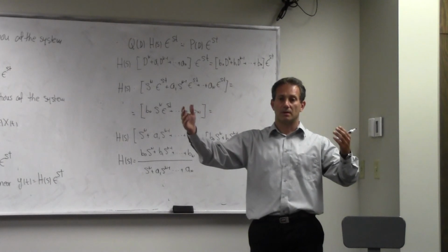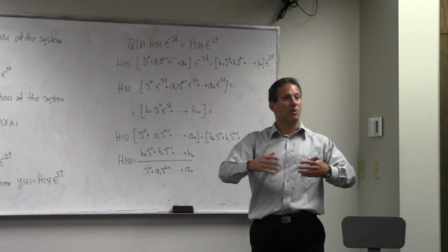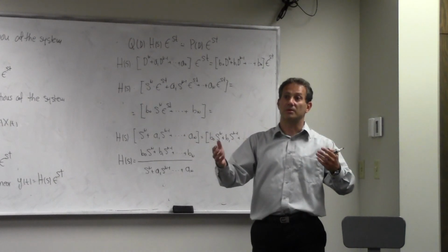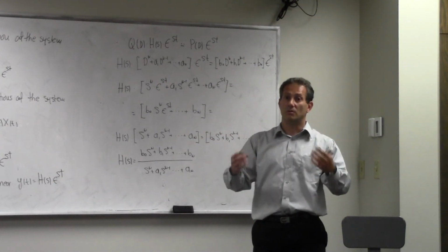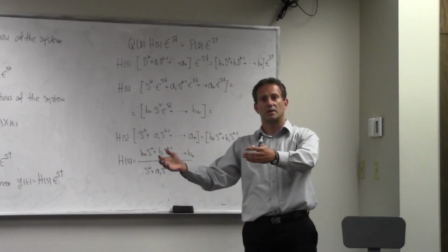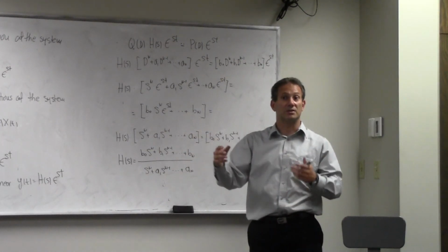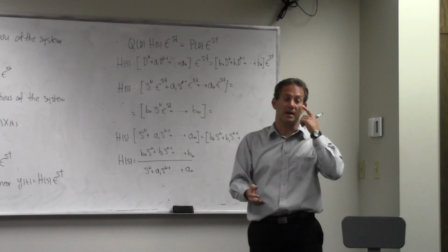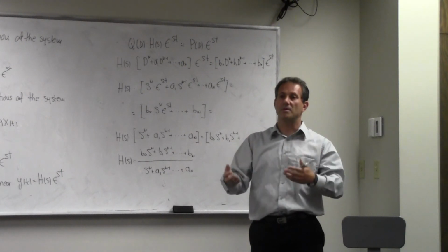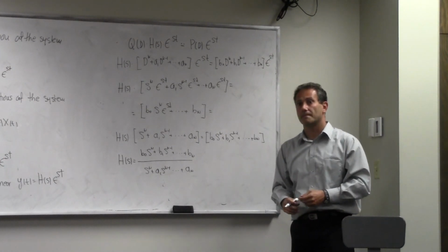Going one step further, what we're going to learn is to take any signal and decompose it into sinusoids. And we're going to do this to determine the output of the system to an arbitrary input. We're going to take the input, decompose it into sinusoids, obtain the response for each one of the sinusoids, and then put them back together to get my signal at the output. It seems a little bit roundabout, but it's the foundation of our frequency domain analysis. And that gives us a lot of insight in many problems. So the input signal can be any signal.